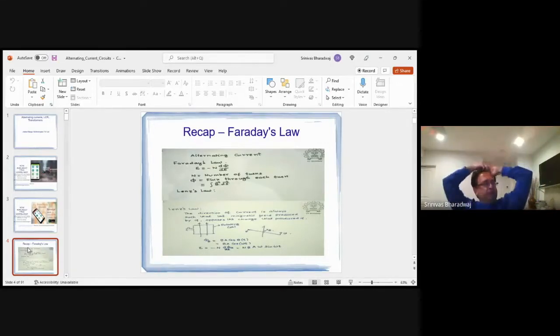So these two are the effect of a current producing a field. Now, if that current is changing, or if it is caused by what is known as electromagnetic induction, then dB changes instant to instant. What does that mean? There's a time varying field. When there is a time varying magnetic field, there is time varying flux. What is flux? Flux is B dot dA. Flux is a scalar.